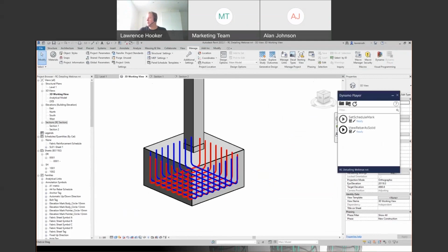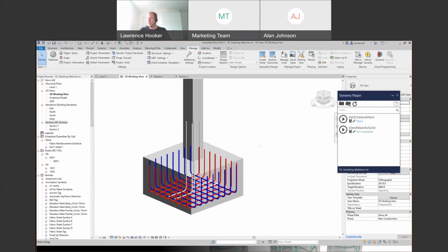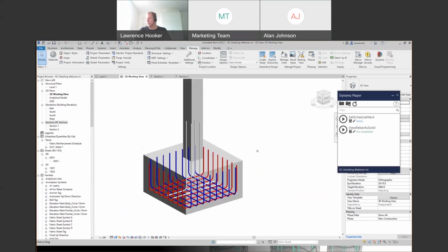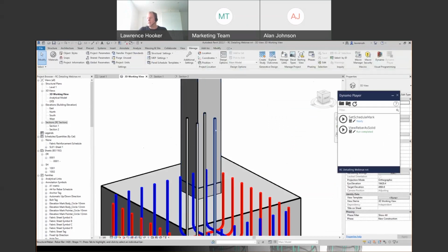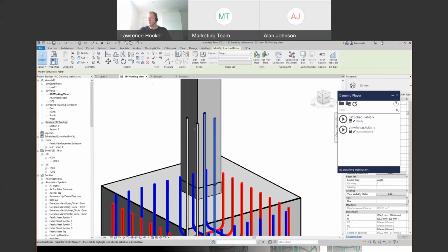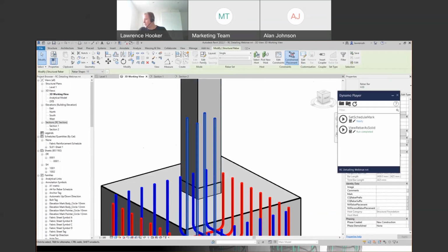So now I'm just going to run the script, set view rebar as solid, and we just simply click that tool, and you can see now straight away those bars are solid in the active view. Once again in here, I could then go ahead and start selecting these starter bars. Perhaps something like this. Let's grab all those bars in there. And of course, the layer that these are sitting in is now B3.